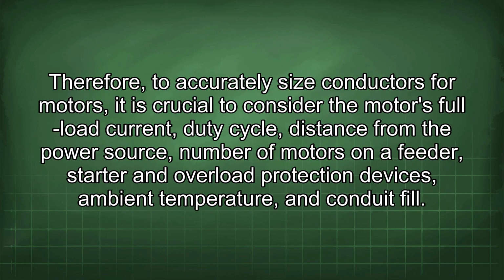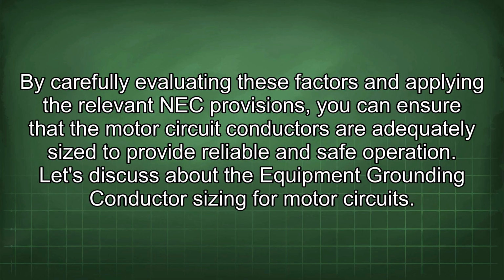Therefore, to accurately size conductors for motors, it is crucial to consider the motor's full load current, duty cycle, distance from the power source, number of motors on a feeder, starter and overload protection devices, ambient temperature, and conduit fill. By carefully evaluating these factors and applying the relevant NEC provisions, you can ensure that the motor circuit conductors are adequately sized to provide reliable and safe operation.